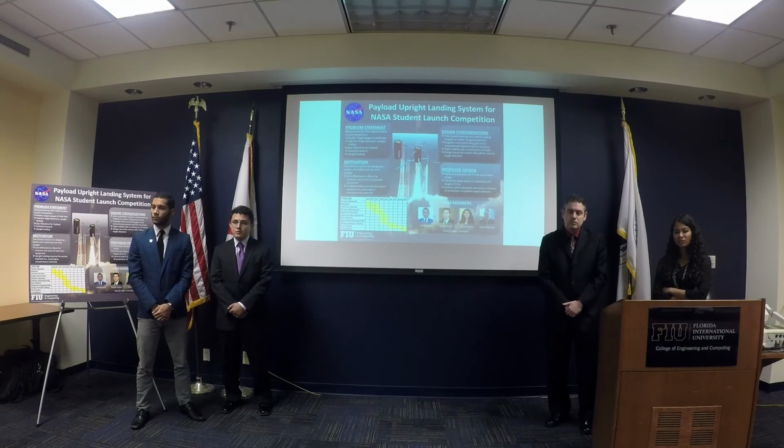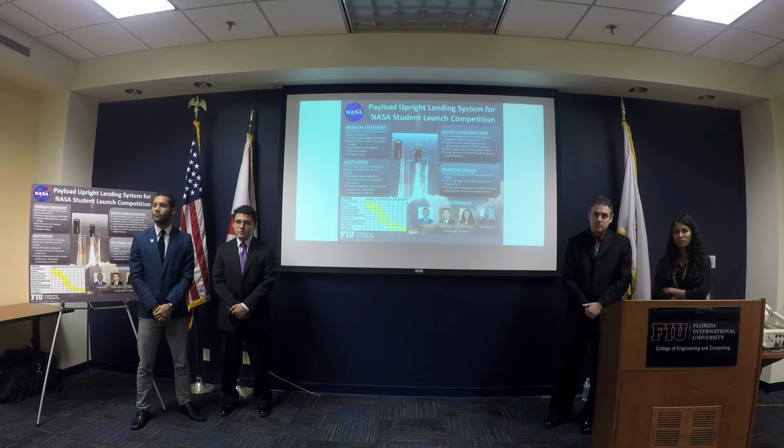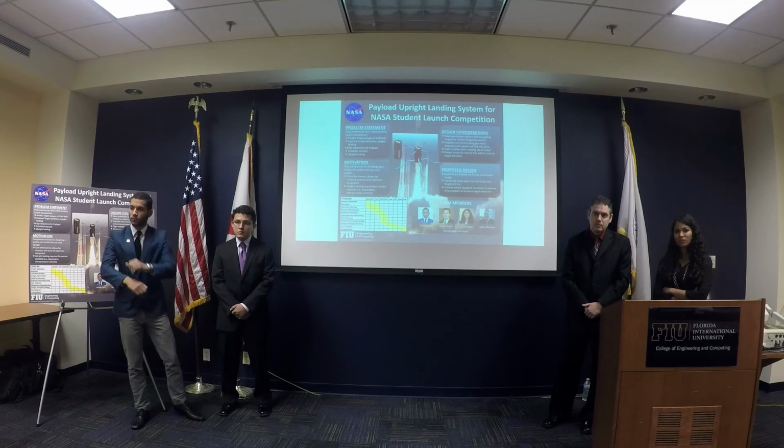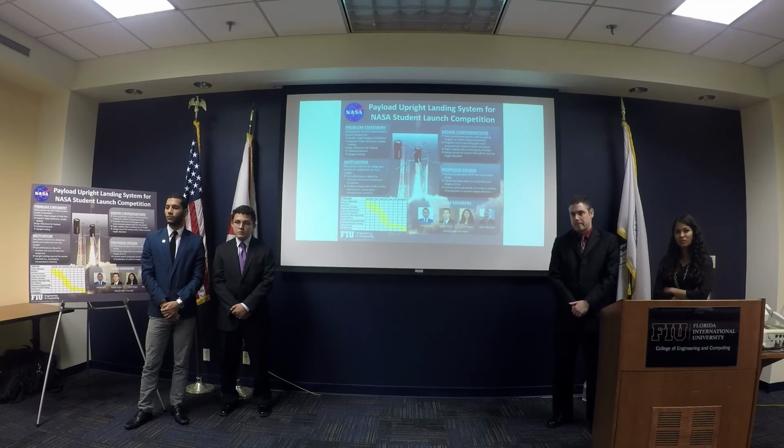So usually, it looks like your primary mission in this case is to land the rocket upright, and if you have one fault in your system, you would fail because you have one fault. It's not a very robust design, so usually you have two strings of whatever form of ejection you're using. Like if you're using pyro to eject, it will usually eject unless the line is damaged, in which case your secondary line will activate and you eject your legs.